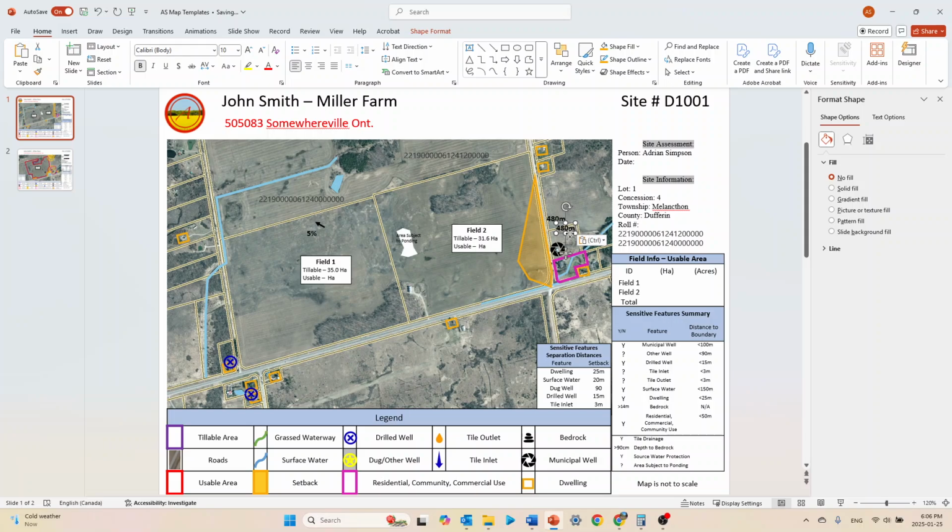I'm going to duplicate that, and that's going to be 141 meters from that tip to my road. Again, I will add lines to ensure that it's properly marked. Although I put that there, due to the fact that that's ponding anyway and there's a surface water setback, I'm going to make that go straight across. So there's no room for error.